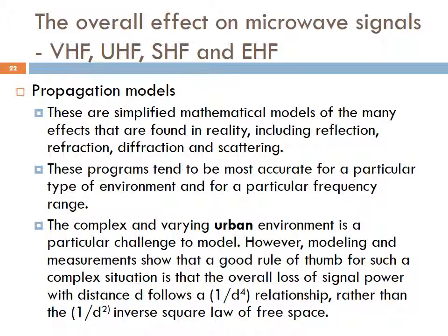The complex and varying urban environment is a particular challenge to model. However, modeling and measurement show that a good rule of thumb for such a complex situation is that the overall loss of signal power with the distance d follows a 1 over d to the power 4 relationship, rather than the 1 over d squared inverse square law of free space.